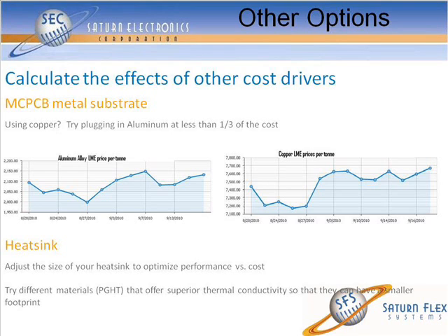And I think Intellectual pointed out yesterday, while there's about 2.5x more performance in copper versus aluminum, the aluminum is so much more thermally conductive than the package above it, it really doesn't behoove you to go to the copper and spend the money in many cases. The other thing is, you could also use that calculator to reduce the size of your final heat sink. Again, a cost saver without affecting the final performance.